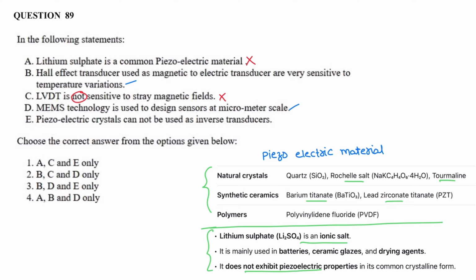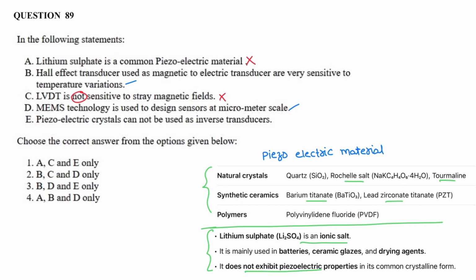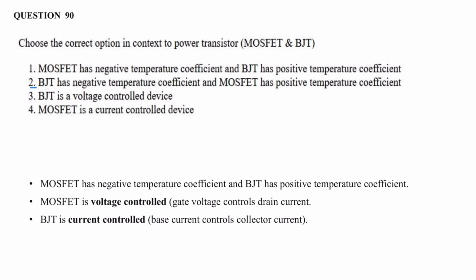Statement E. Piezoelectric crystals cannot be used as inverse transducers. Piezoelectric crystals can work in both ways. A transducer is mechanical to electrical, inverse transducer is electrical to mechanical. It can work in both ways. Statement E is incorrect. The correct statements are B and D. So, there is no correct answer from these options. Next question.